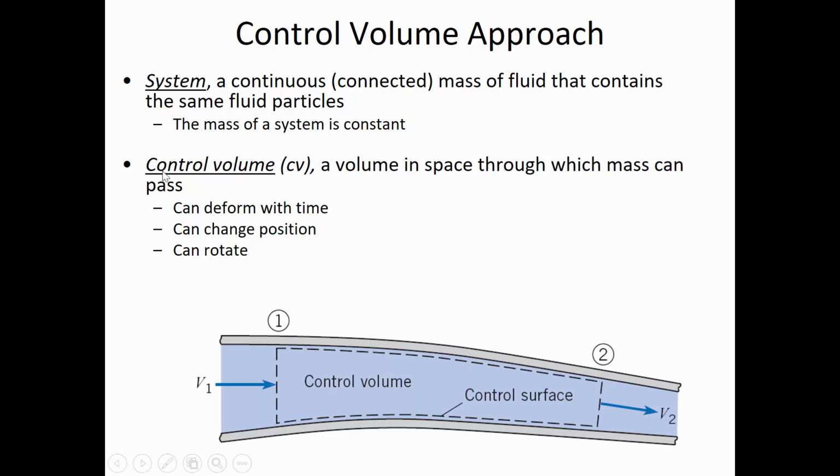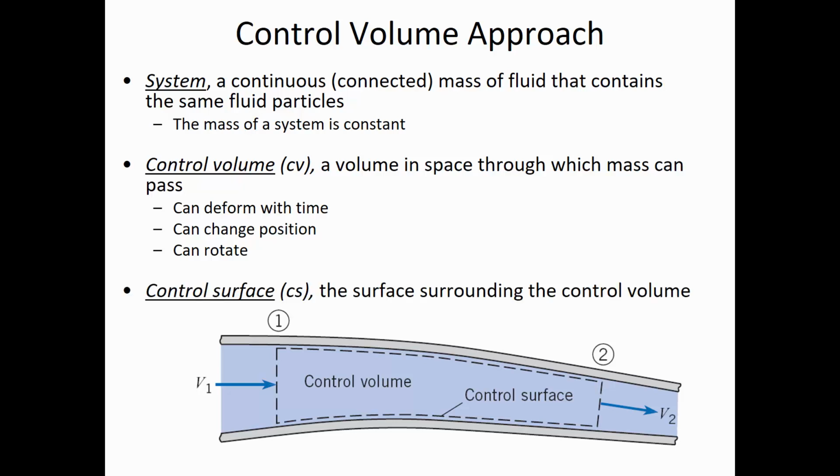The control volume is that space that we're going to be tracking the system's movement through. And the control surfaces is just the outside surfaces through which the system can pass. So their abbreviation CV we'll use as control volume, CS we'll use as control surface, and these same abbreviations will be important in Chapter 6 when we start talking about fluid momentum.